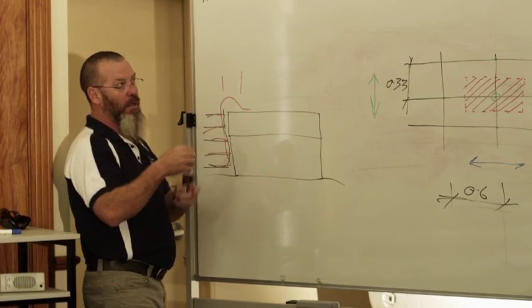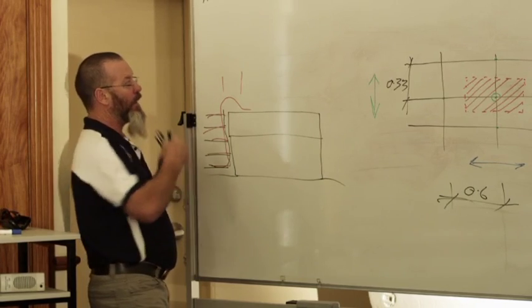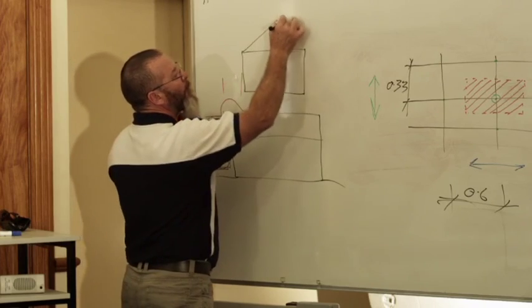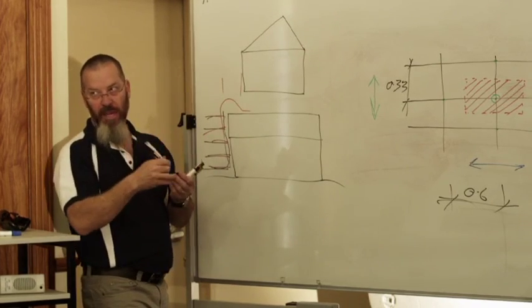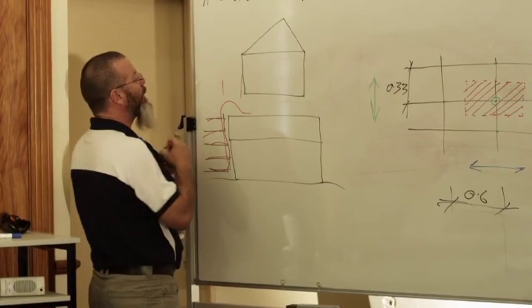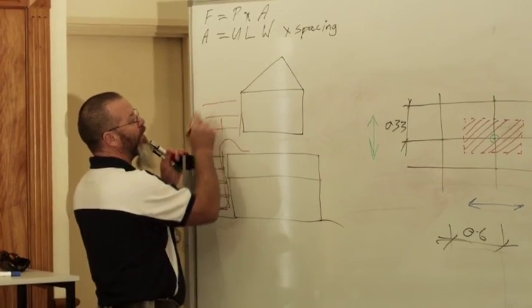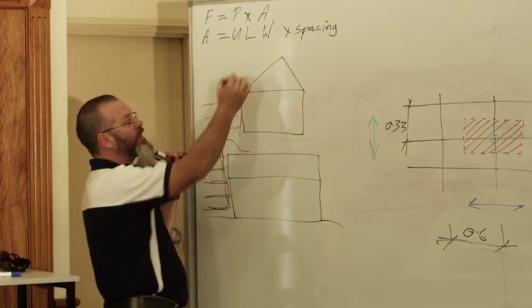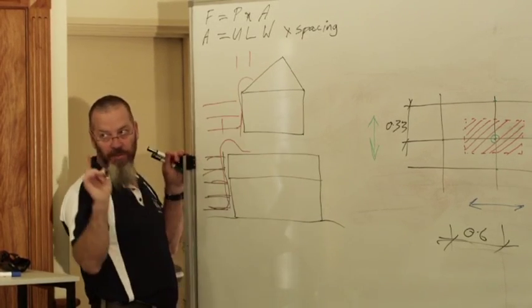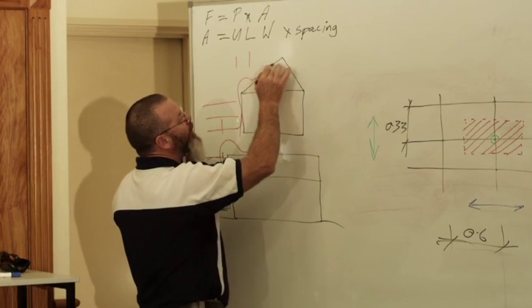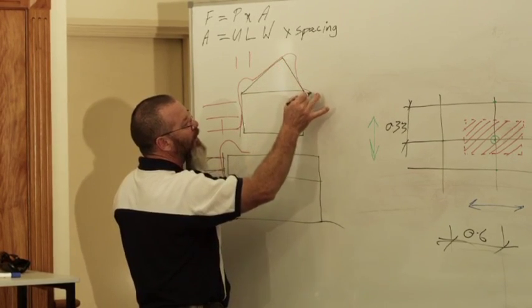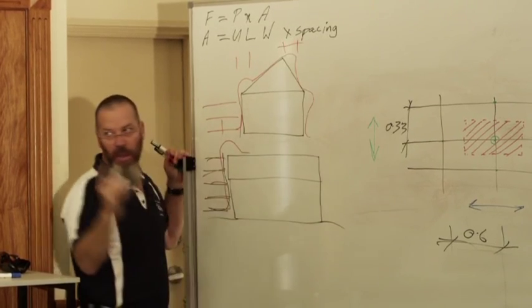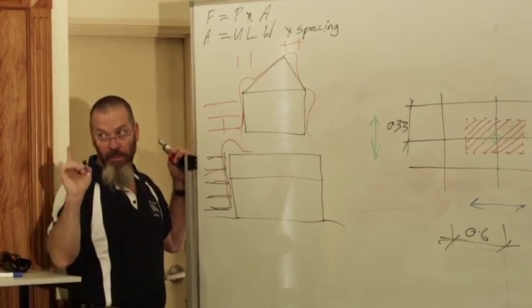You have a look at a stick roof. Badly built stick roof, but it's a stick roof nonetheless. Where you've got the wind arrows coming on the side of the building. So what's actually happening, you're getting a small Bernoulli happening here. So that's an edge within 1.2 metres of the fascia. And then when it comes up the roof, it goes over like that because of this viscosity, over like that and back down. So there's another Bernoulli as well. So that 1.2 metres at the ridge.